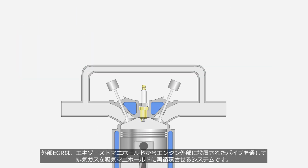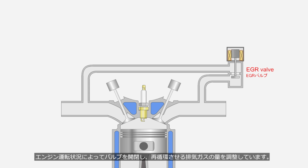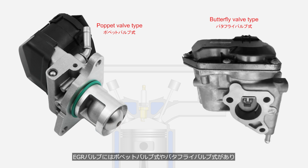External EGR system is a system that recirculates exhaust gases from the exhaust manifold to the intake manifold through a pipe installed outside the engine. An electronically controlled EGR valve is installed along the exhaust gas passage, and it opens and closes based on engine operating conditions to regulate the amount of recirculated exhaust gas. EGR valves come in types such as poppet valve and butterfly valve, and they open and close based on signals from the engine control unit.